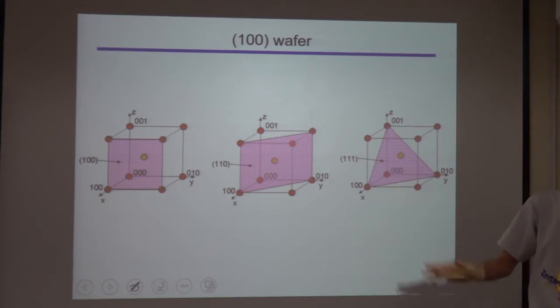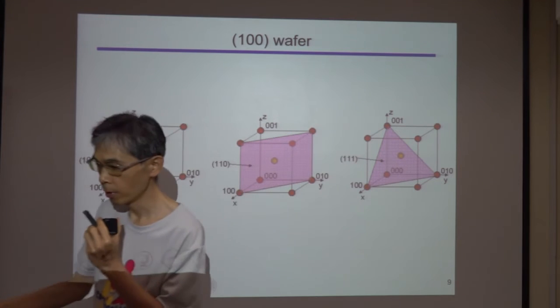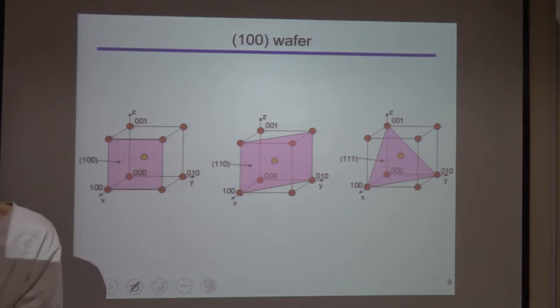And for the wafer, when we fabricate, the wafer foundry makes a wafer. The wafer looks like this, a cylinder. This is the raw material of the wafer, not the silicon wafer. We can cut this cylinder into slices to create silicon wafers. You can cut it this way, or the other way. There are many ways to cut the cylinder. If the top atom surface is a 100 surface, you create a 100 wafer.